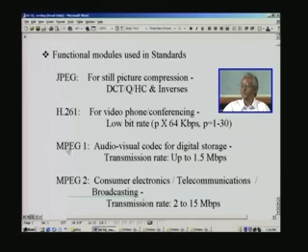And all these standards listed are basically the same; DCT is going to be used, and this is for still picture compression. The modules that we will be using and designing will be the DCT, then quantization, next is what is called Huffman coding, which also goes by the name VLC, abbreviation for variable length coding.